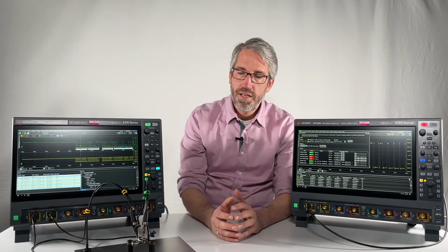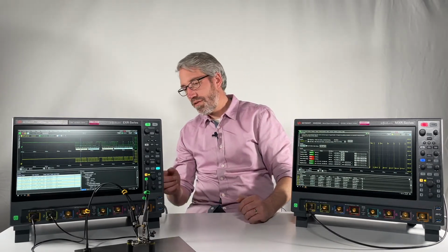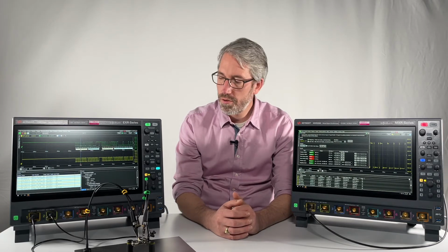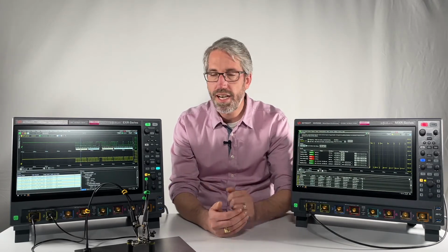On top of that, unfortunately you can't see that from the front, there's a connector here at the back for 16 digital channels, and you can turn on these 16 digital channels without compromising the performance of the 8 analog channels. So in total you have 24 channels available with the full performance of all these channels. Now think about this. You can look at more signals than you could ever before on an oscilloscope simultaneously. And there is more actually to these two oscilloscopes.